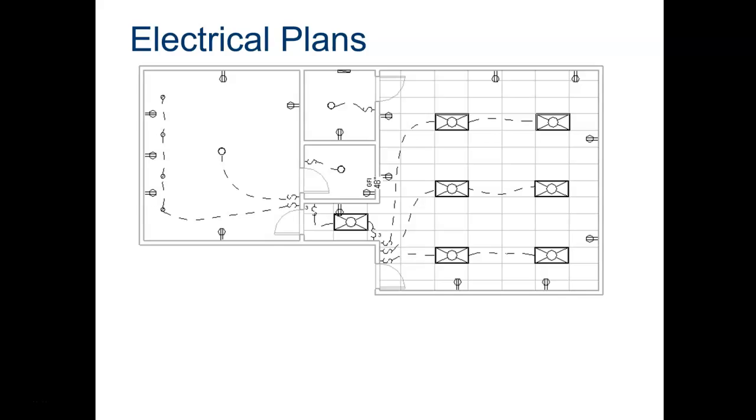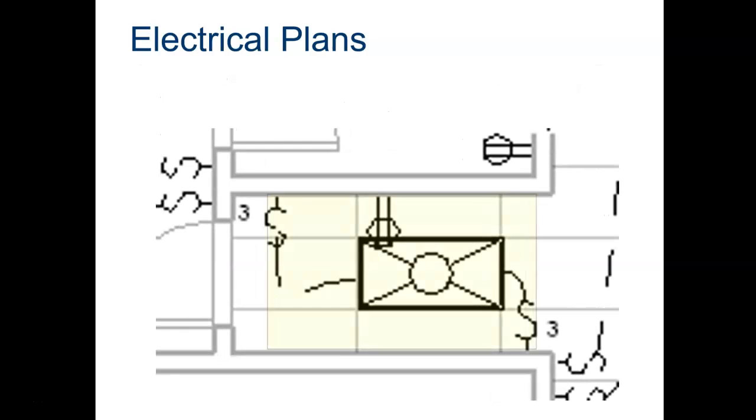The dashed lines are switch legs that represent the wiring between a switch and the electrical components that control it. In this design, all of the lights are controlled by switches. Outlets and other wired equipment can also be controlled by a switch. Note the use of single switches in most cases, except where two switches control the same light or group of lights, where a three-way switch is used. A small 3 next to the switch symbols indicates a three-way switch.